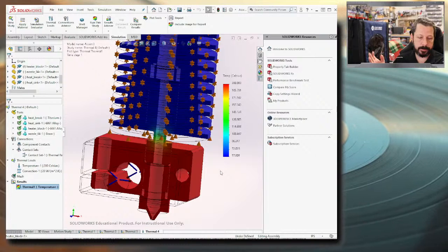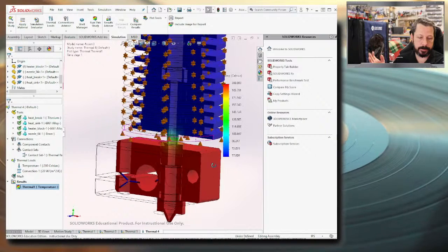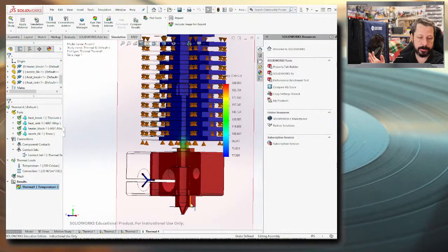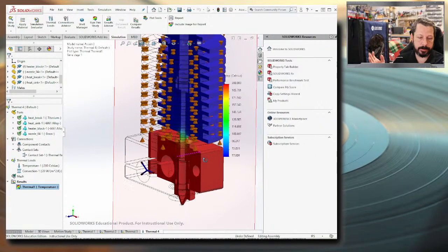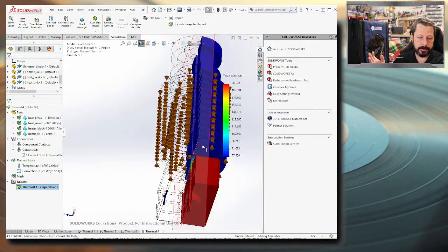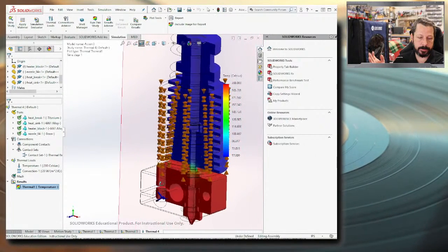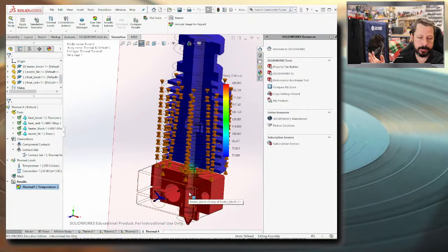So there's always a possibility of one of those kind of things happening, and then you've got an entire replacement job to do. The other possibility is that you get too close when you reassemble, between the heat block and the heat sink. They conduct heat instead of just radiating heat between each other, and that can cause you more clogs. So understanding the way this works will probably help you troubleshoot most of the printer problems.